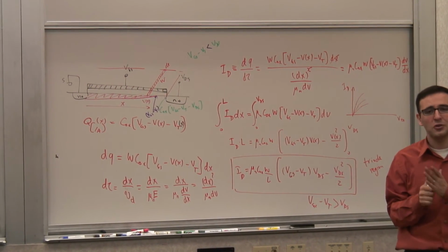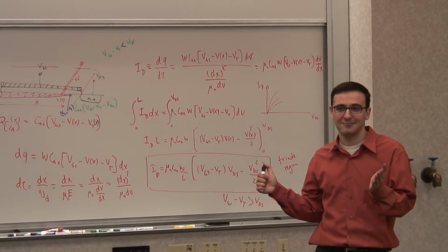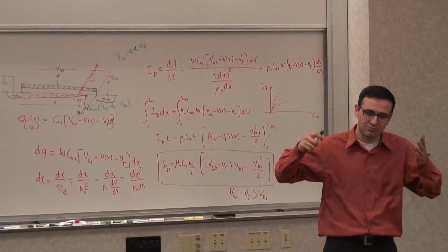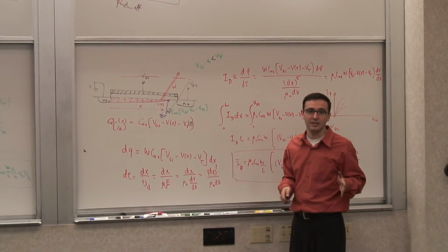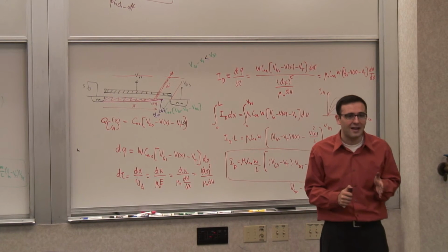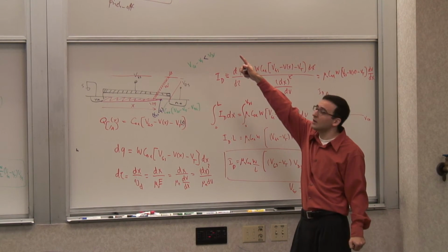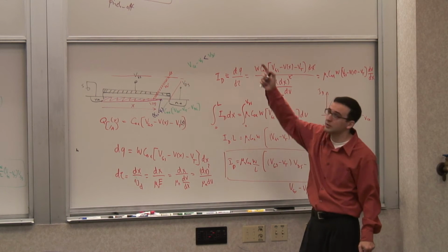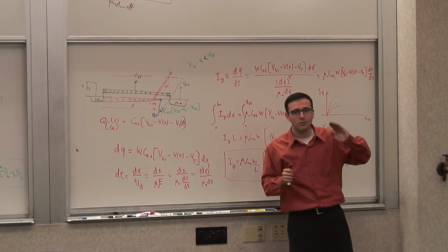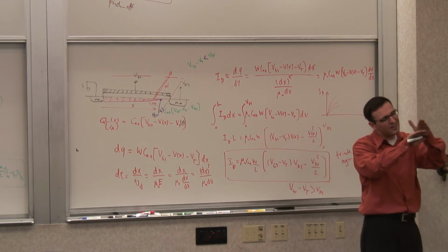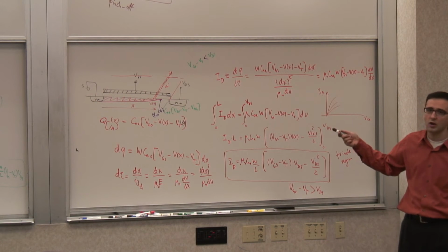And in fact, you can write expressions for that. And interestingly enough, you can actually solve the integrals. I mean, you can integrate them analytically. They look really ugly, and they give you an equation that's not like this. They don't give you a square law behavior, like the one you see here in the pinch-off region. They give you something else. But if you plot them next to the square law, they're close enough. That's called the bulk charge theory.